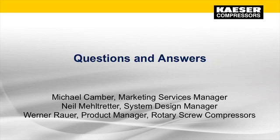Okay, great. Werner, I think this next question is for you. Can I add heat recovery to my current system? The short answer is yes. Some compressor manufacturers offer retrofit kit options that are great for existing systems, but keep in mind, check your current equipment. If it's outdated or inefficient, it won't get you as good a return on investment. Do the math. In some cases, you might be better off going with new equipment with an integrated heat recovery option. Thank you very much, Werner, for that answer.